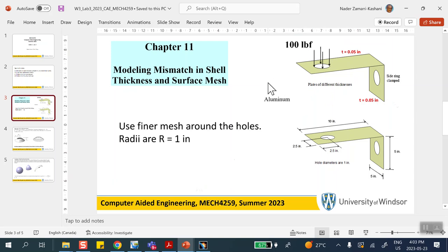Notice that this does have a plane of symmetry, and basically you cut it along this line, along this length, and vertically down. So you have the left side and the right side, and you're going to model the problem like that. So I'm going to use planes of symmetry as you're expected to do on the test, and also use the most appropriate element, which in this case obviously is a shell, because it's a shell section that you're doing. All right, let's go ahead and do that, and then I'll come back and talk about the problems for lab 1 and lab 2 later on.